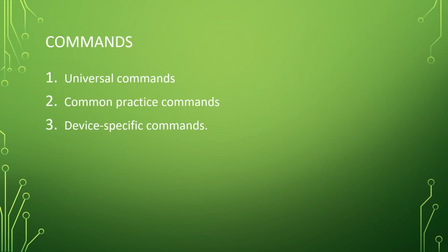So we do have lots of commands that communicator can send. We have universal commands, which deal with manufacturer and device type, primary variable, units, current output, range, variables, messages, all types of things like that. We have practice commands, which are setting variables, dampening time constant, device range, calibration, self-tests, resets, all sorts of things.